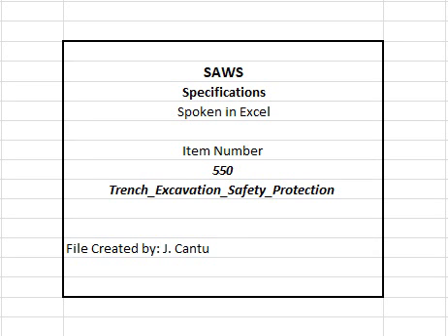550.3 Submittals. Contractor shall submit manufacturer's product data, instructions, recommendations, shop drawings, and certifications. All submittals shall be in accordance with engineer's requirements and submittals shall be approved prior to delivery. 1. Submit a safety program specifically for the construction of trench excavation. Design the trench safety program to be in accordance with OSHA 29 CFR standards governing the presence and activities of individuals working in and around trench excavations.